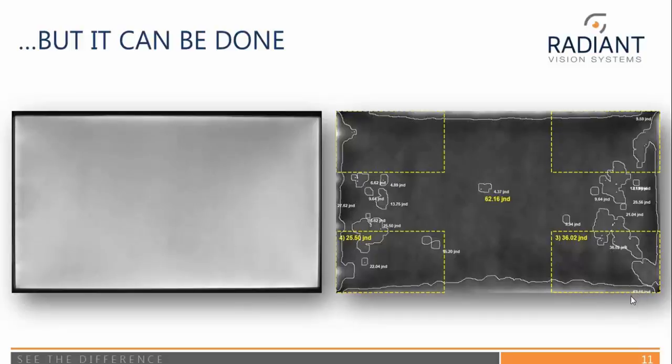In this case, the most obvious defects are along the left edge. When looking at the original image, you can spot some bright spots. In this case, the backlighting is along that left edge, and that's part of the issues there. What's a little bit harder to spot is maybe the Mura towards the center of the image. Going back and forth between the analyzed image, which is a contrast image, and I'll get into that more later, it's easier to spot going back and forth with the original image and that image.